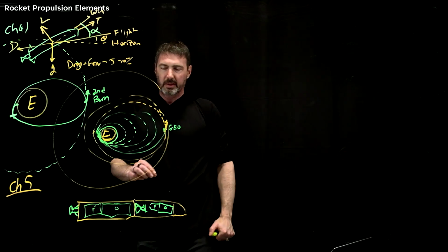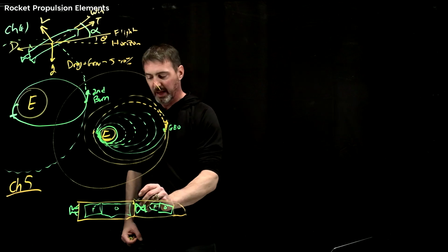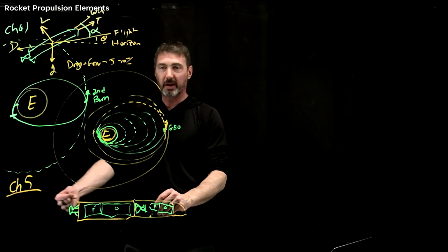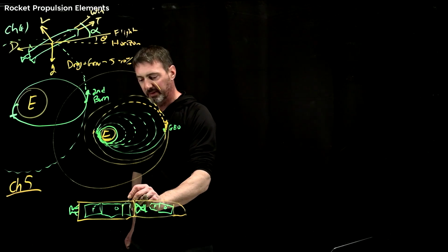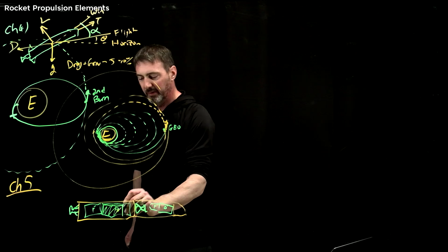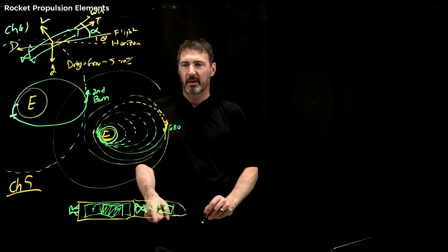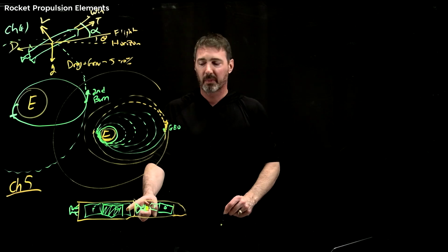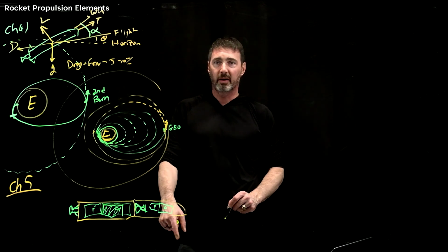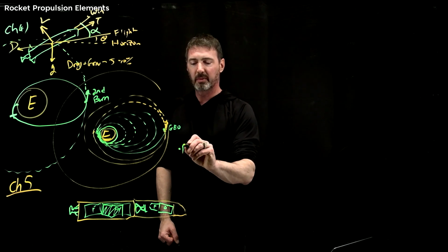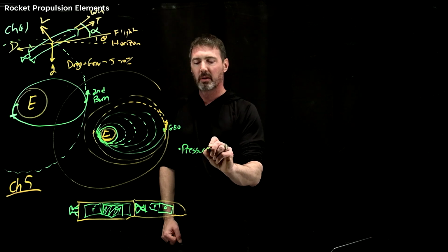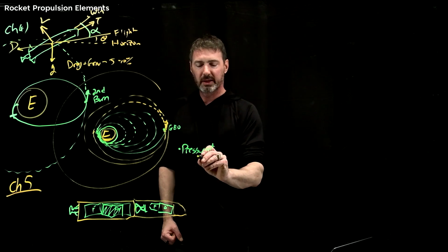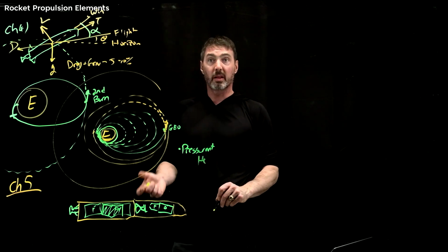Okay, now what's happening as this rocket is burning, so gravity's down, let's say this ox tank is actually, here's the amount of liquid that's left. If you have this whole gap right there, something's got to fill that gap. So you also have to carry on board pressurant. So I'm going to add it here. And usually pressurant is helium because it's light.